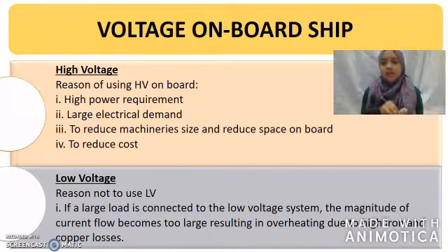Okay, the reason why low voltage is not used popularly nowadays is because if a large load is connected to the whole system, the magnitude of the current flow becomes too large, resulting in overheating due to high iron and copper losses.